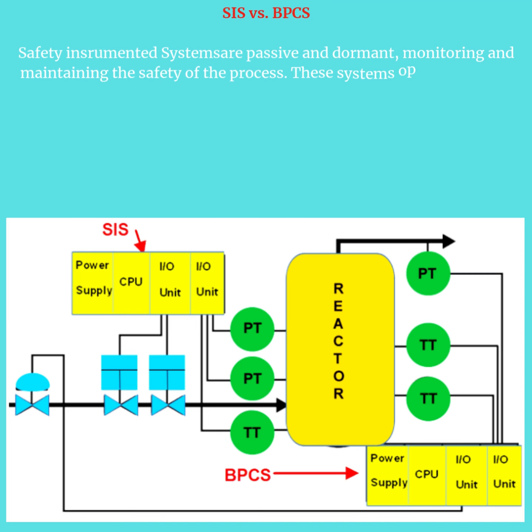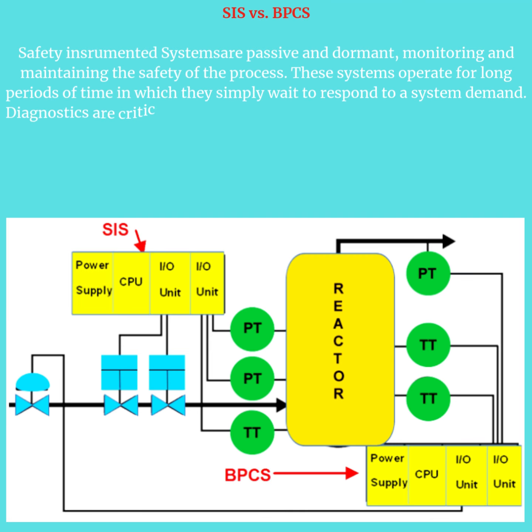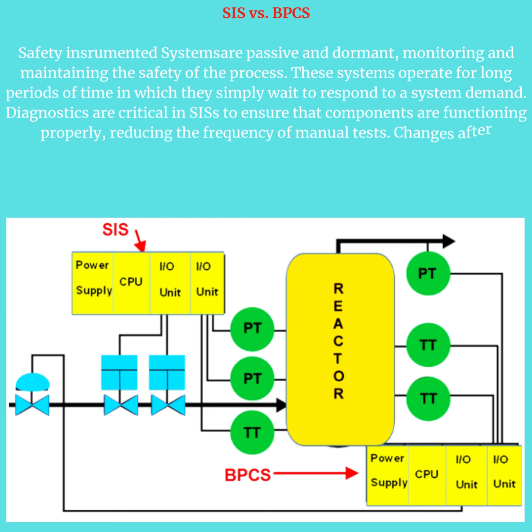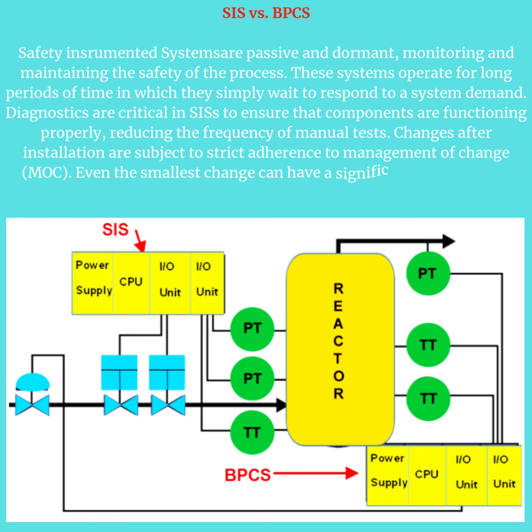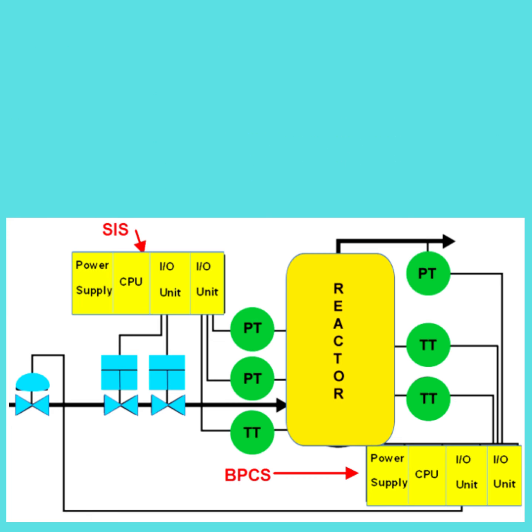These systems operate for long periods of time in which they simply wait to respond to a system demand. Diagnostics are critical in SISs to ensure that components are functioning properly, reducing the frequency of manual tests. Changes after installation are subject to strict adherence to management of change (MOC). Even the smallest change can have a significant consequence.